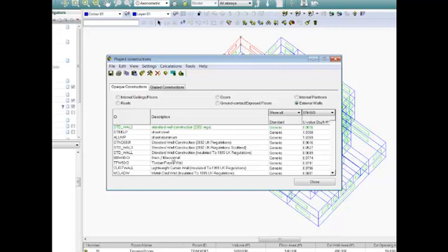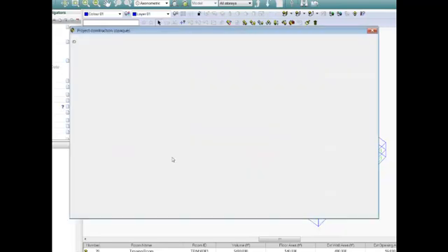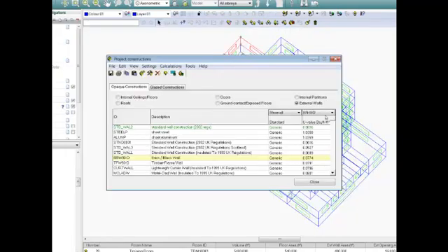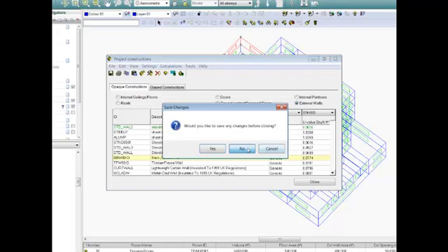I can also edit, if I want to take it further, my wall construction. So I may want to test what happens if I have, for example, my insulation. What if I take that from 2 inches to 3 inches? Because many times you'll find that insulating the building more is more effective at reducing the energy consumption than adding a large PV array. So it's really about comparing all of these technologies and even just making the building more insulated and seeing what is the best way to improve your building design.